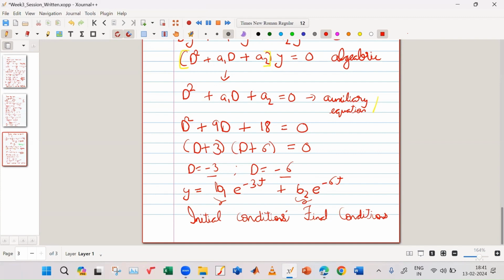When you are solving an electrical circuit, like in the ones which you will do in the examples, you are writing the differential equations. From the circuit, you must determine what are the initial conditions, what are the final conditions, and then you solve the differential equations, then you substitute those conditions, and then you get the values of b1, b2, etc. And then you can proceed. Then you get your solution. So it is a bit tedious, I agree. There's an easier method, which is Laplace, which you will learn later.